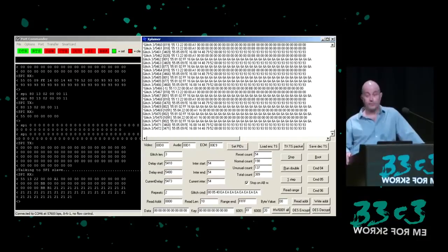The 7-byte, 56-bit keys stored in RAM straddle these dead addresses. So a potential exploit that could cause a linear dump of memory will be stopped before a complete key is ever read. When the chip is reset, it means having to glitch in again because my code payload exists only in RAM and there is no way to hook in a permanent backdoor.